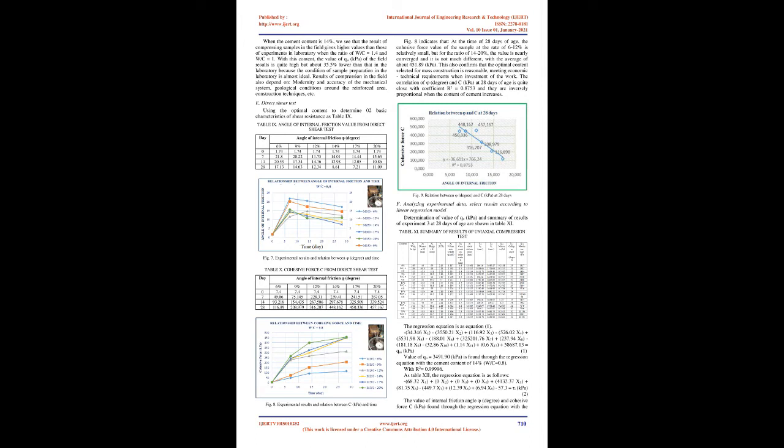D. Comparison with field experimental results. Based on the results of 4 experiments in laboratory, the ratio W/C equals 0.8 and the cement content of 14% will be the optimal content for mass construction. To verify the feasibility of this option, the comparison with the field results is implemented as Fig 6. Fig 6. Comparison of the value of CHU, kPa, between lab and field experiments.